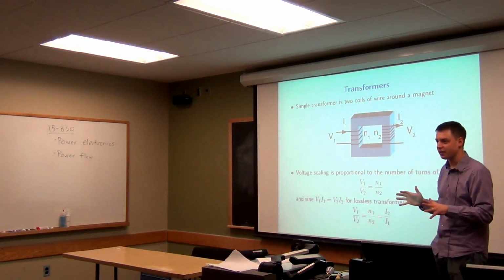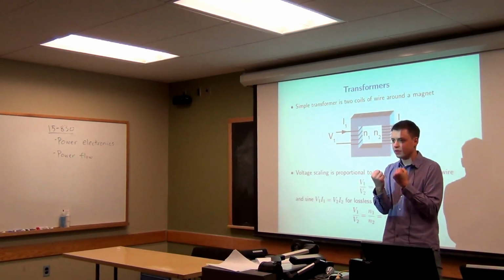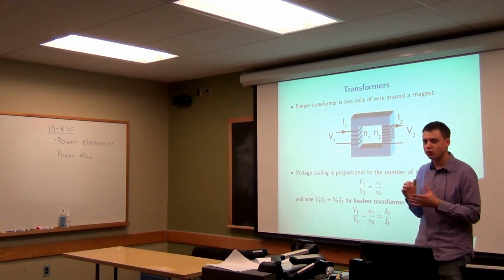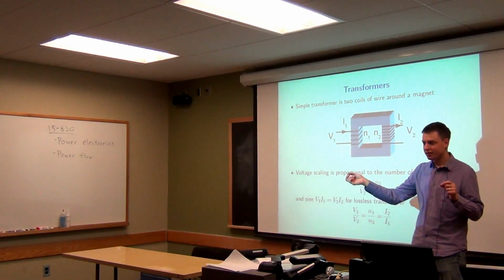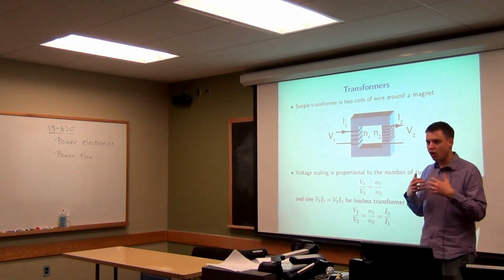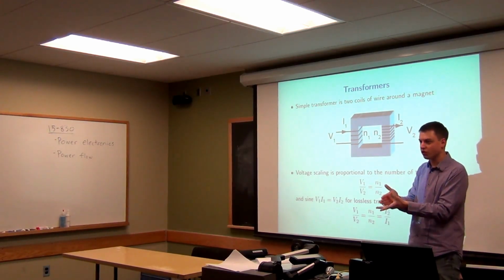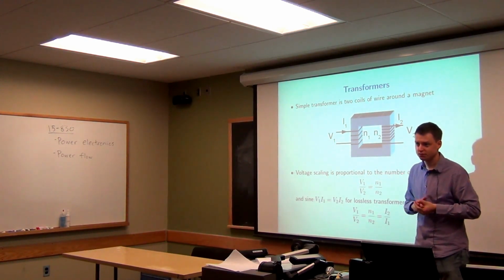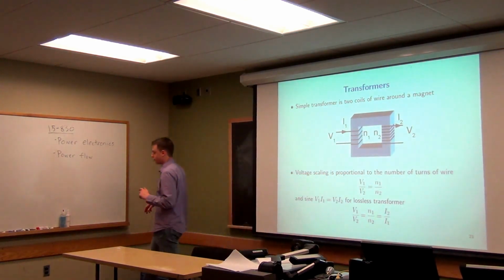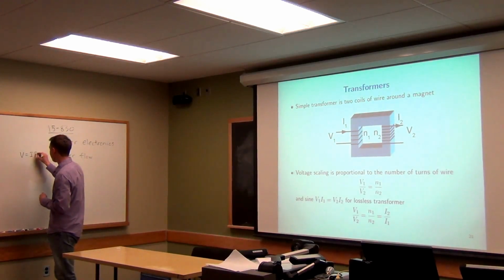The biggest nicety of this is that what really causes loss in a wire is not power. It's actually the current flowing through it. Current is the actual amount of charge that's flowing through that wire. And the losses you get from that wire are going to be proportional to the current flowing through it. In fact, that just comes from Ohm's law, right? Ohm's law says V equals IR.